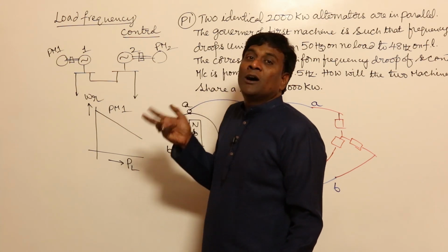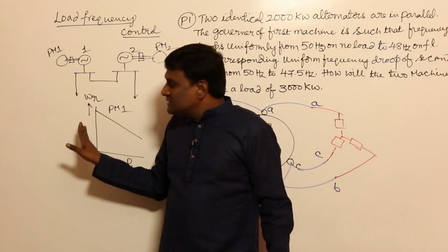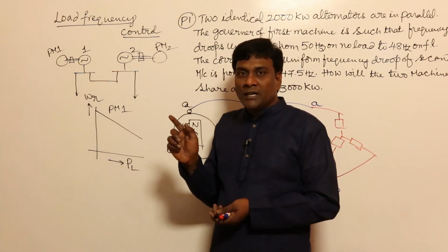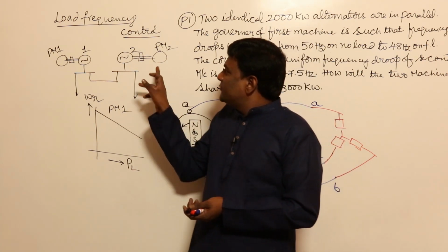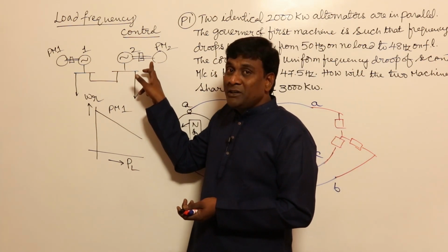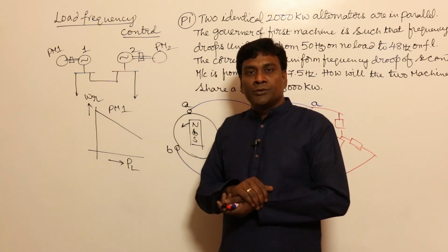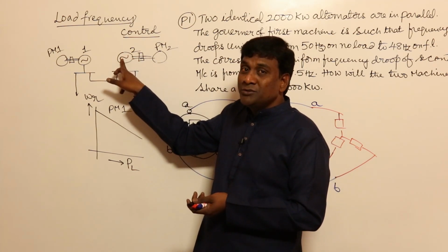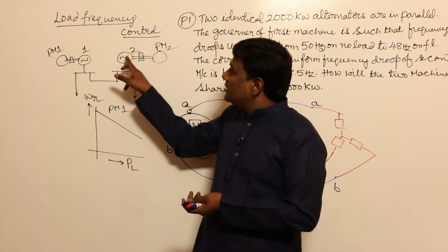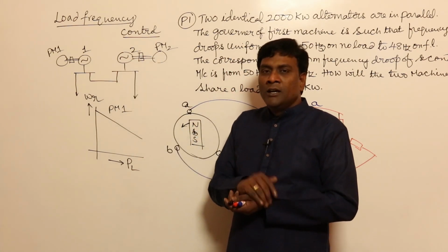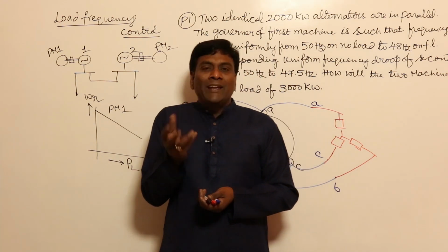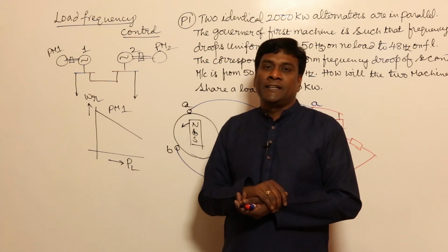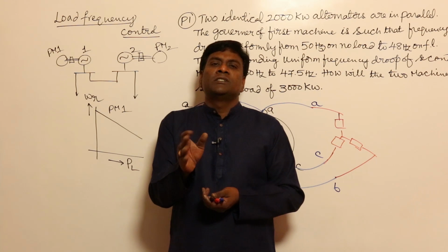Now we have to convert this into electrical terms, because we are electrical engineers, so let us map this from the mechanical domain to the electrical domain. One great interview question: if speed reduces here, the magnitude of voltage will be reduced, and also the frequency will be reduced. Because if speed reduces, the induced voltage generated here will be reduced, no? And frequency also will be reduced. Now the interview question is, why do we consider only frequency variation, and not voltage variation?